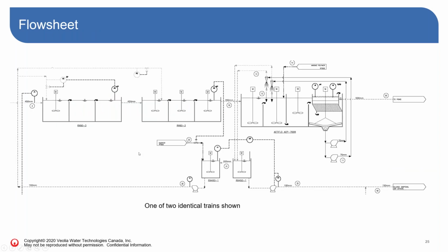The treatment system is simpler than the previous case study. Basically, it's 2 reactors in series, just to give us retention time and an active flow. There is no organic component there. It is a metal mine, so there's nothing. It was done with lime as the alkali, so that's the little difference there for the lime addition, but it's fairly straightforward.